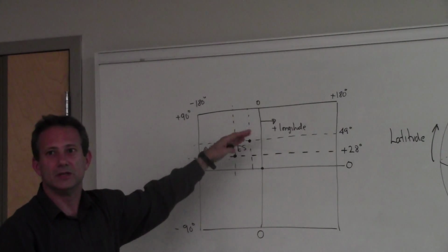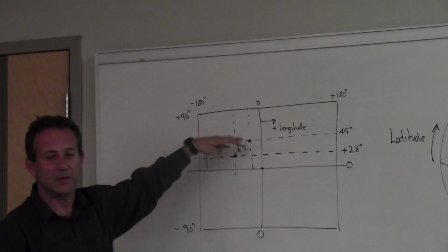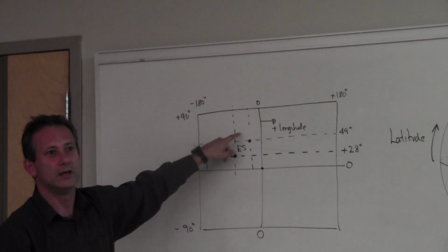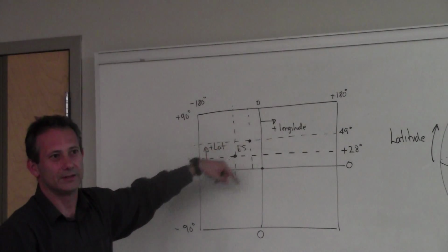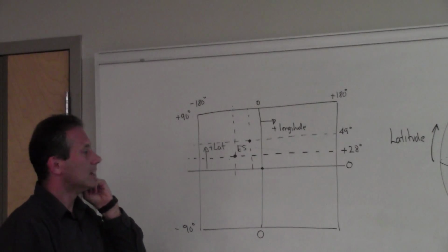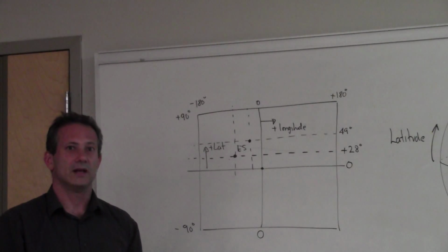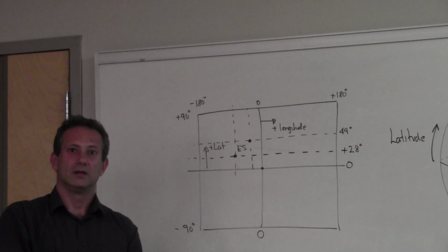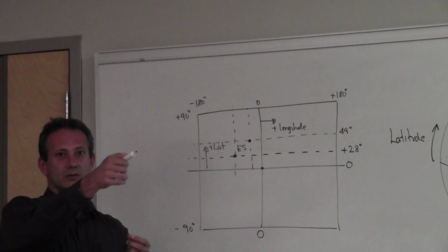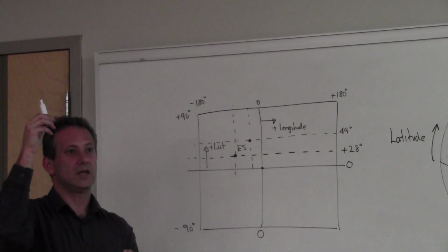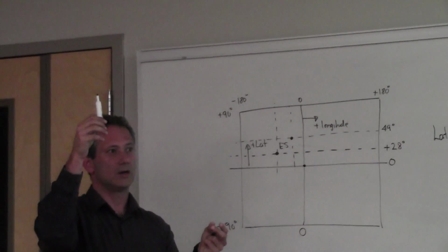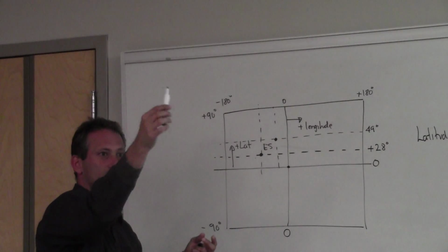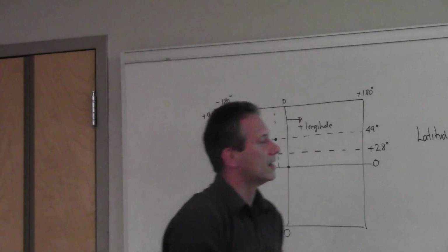Somewhere around 40-something degrees, right? If it will do the precise calculation using the spreadsheet, but it cannot be 135 degrees, right? You can see from this map. Now, this is a low orbiting satellite. So, what do you expect your azimuth and your elevation to be? Very close to the horizon, right? Because except when it's really at the same latitude and longitude where you are, this satellite is almost all the time on the horizon, right? Because it's flying really low in the sky.